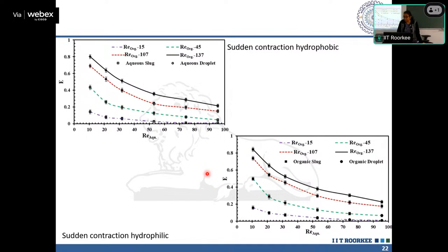In the second case, it is hydrophilic, so water is the continuous media, and we have slugs of toluene having much lower viscosity than the continuous medium, always around half. Even through our simulation, which I showed you in my second lecture, the circulation inside a low viscosity slug is always higher, and that is the reason we are getting higher efficiency in this case.